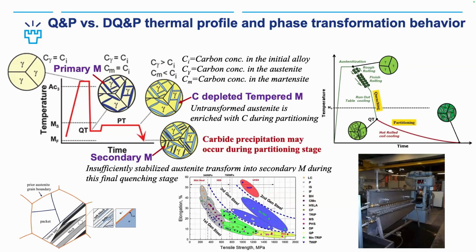During this isothermal holding time, there are several concurrent phenomena occurring simultaneously, like austenite decomposition into bainite, carbide formation, and martensite tempering. This is not an easy job to control all these phenomena, but through proper alloy design, we can control the precipitate formation.